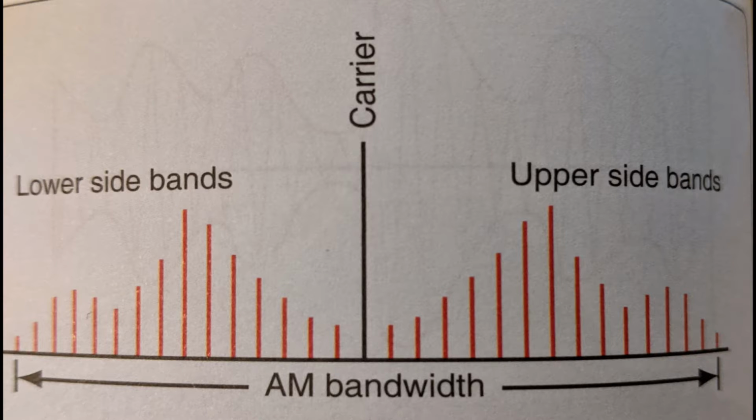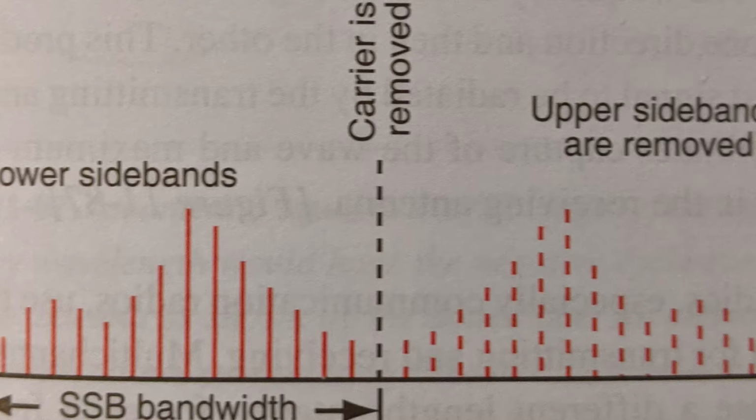Single sideband communication. In radio communication, single sideband modulation, or SSB, is a type of modulation used to transmit information such as an audio signal by radio waves. A refinement of amplitude modulation, it uses transmitter power and bandwidth more efficiently. Amplitude modulation produces an output signal, the bandwidth of which is twice the maximum frequency of the original baseband signal. Single sideband modulation avoids the bandwidth increase and the power wasted on a carrier wave, at the cost of increased device complexity and more difficult tuning of the receiver. Many high-frequency long-distance aviation communications are SSB.